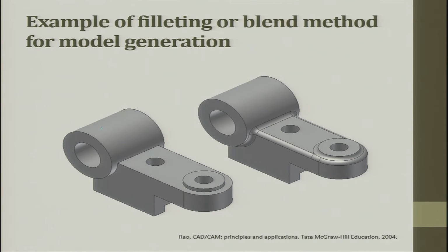objects, we start with a simple primitive. These primitives are chosen and placed at locations. But when these primitives are placed and butt against a flat one, it is always necessary to have a filleting done, such that these points are not the stress concentration points,